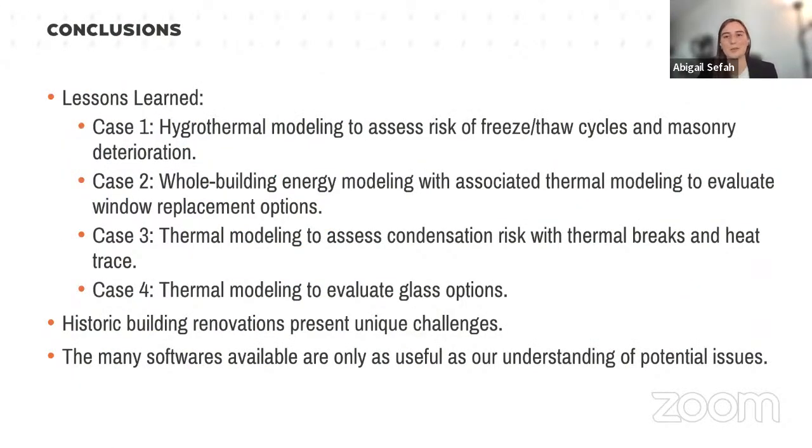So from each of these case studies, we've learned about the importance of using the correct modeling software to evaluate different risks. In our first case study, where they were proposing installing insulation on the inboard side of a multi-wythe masonry wall, we used hygrothermal modeling to assess the risk of freeze-thaw cycles and the associated masonry deterioration. In our second case study, in which a client was proposing remediating or replacing existing historic windows, we used whole building energy modeling and associated thermal modeling to evaluate window replacement options.